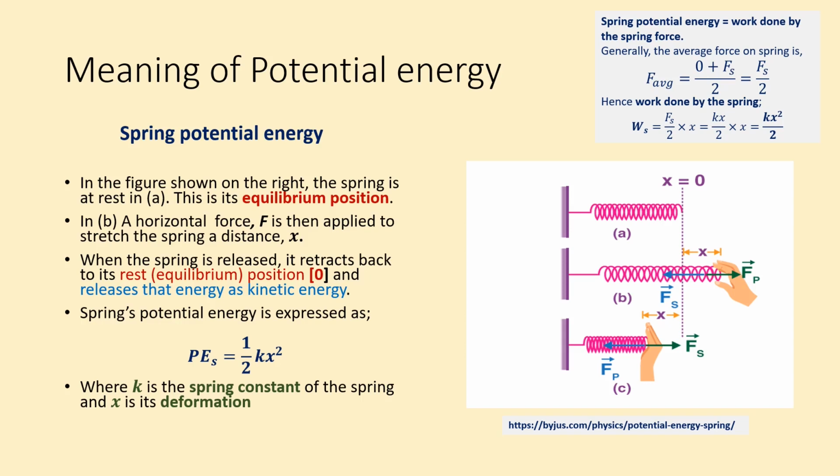If you look at the illustration there, those equations at the top, we're saying that the average spring force applied to a spring is given by your initial force, which is usually 0 as you're just starting to stretch the spring, until you reach the maximum value of the force, whatever you've decided is your maximum stretching force. It may or may not be at the spring's elastic limit. It just depends on how far you decide to stretch it.